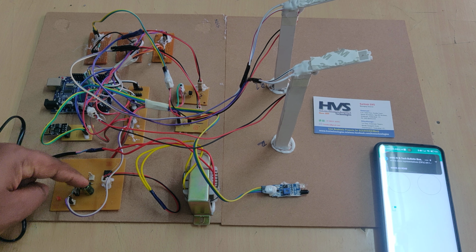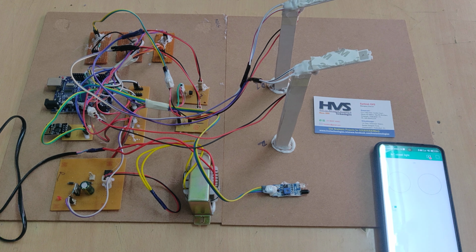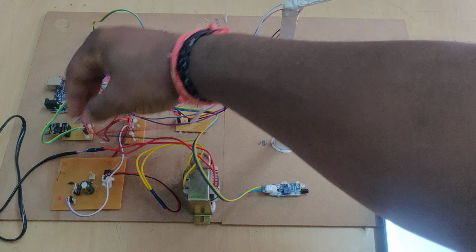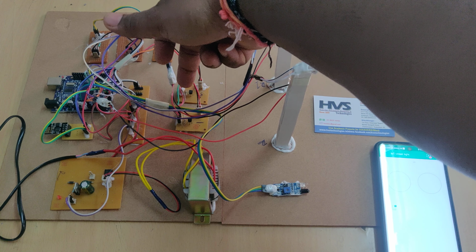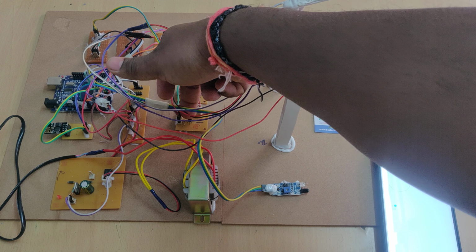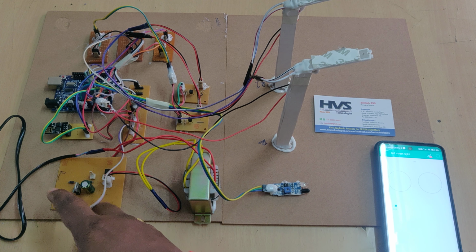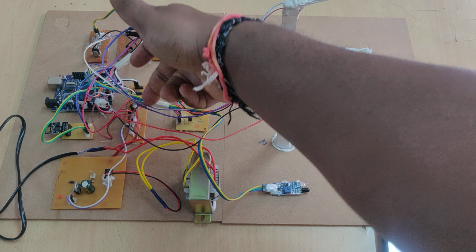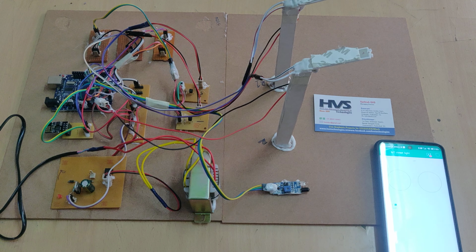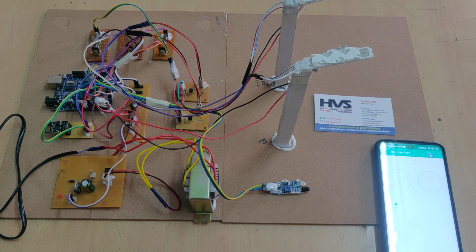Here this 12 volts is the supply voltage for the LEDs. These 12 volts are distributed to the transistor boards. From there, based on the signal from the Arduino Uno, the transistor will allow the voltage at 50% and 100%. And after the regulator, the 5 volts is given as input to this breadboard. This breadboard distributes the 5 volts power supply throughout the input and output modules in our whole project. So let us see the demonstration.